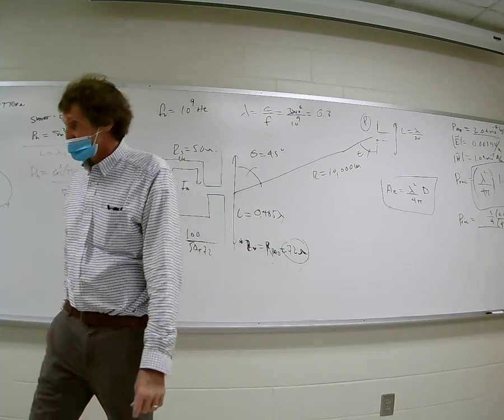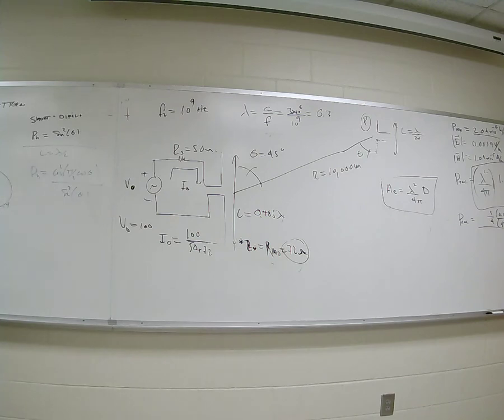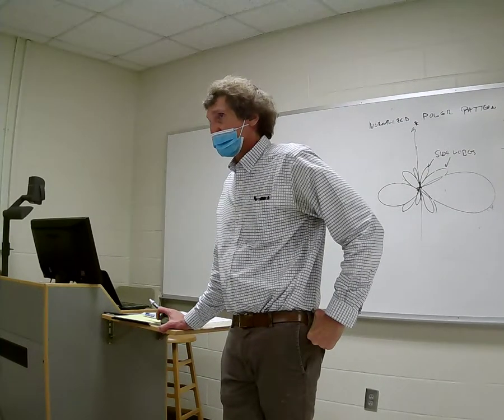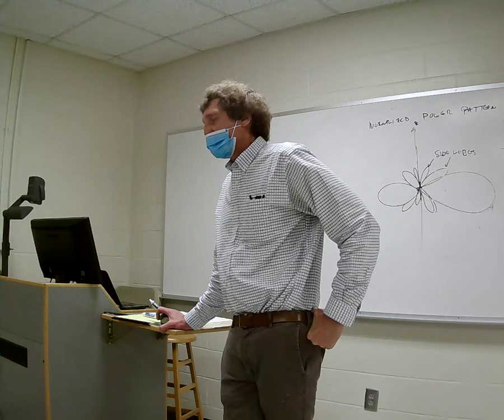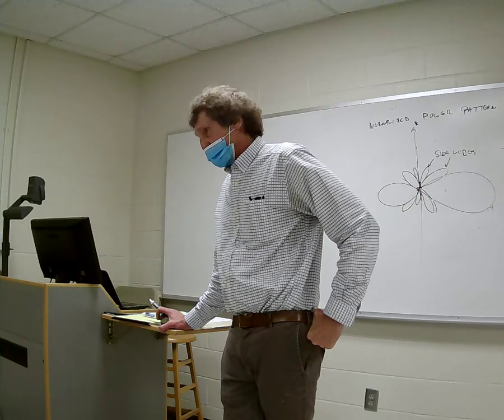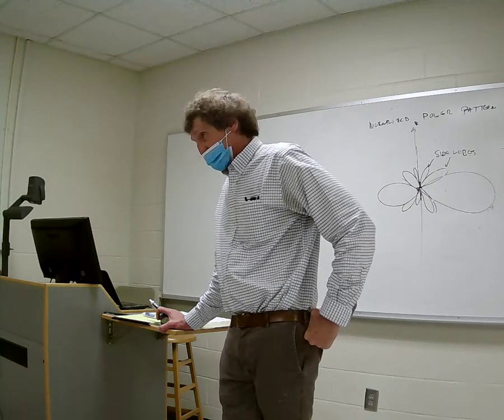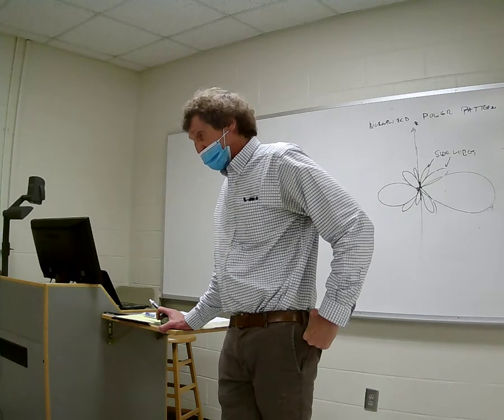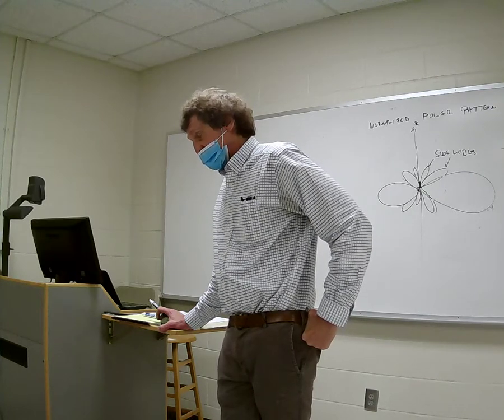Will you be writing the table on page 466 for us? No. I will give you the half wave. And I'll give you the radiation resistance of the small loop. And tell you what, I'll give you the radiation resistance of the short dipole. But I'm not going to give you the gain of the short dipole. I'll give you the gain of the half wave. How's that? Because that's a weird formula.